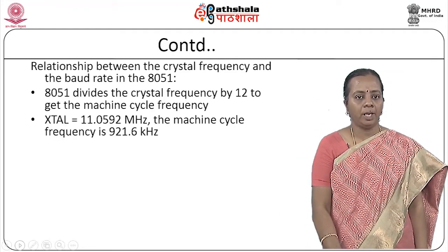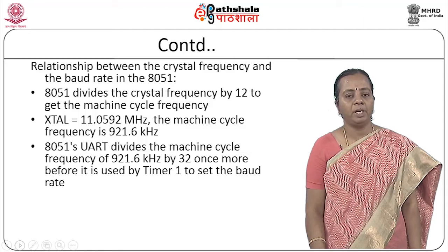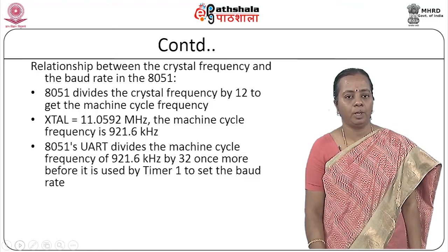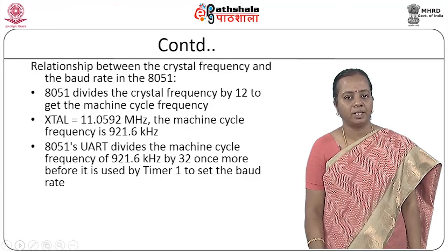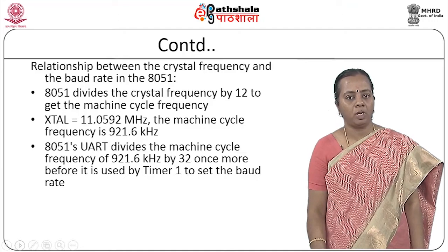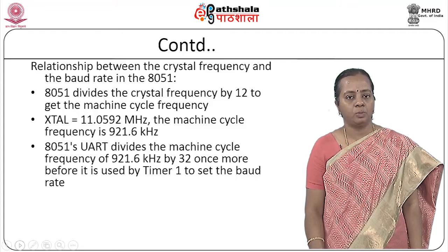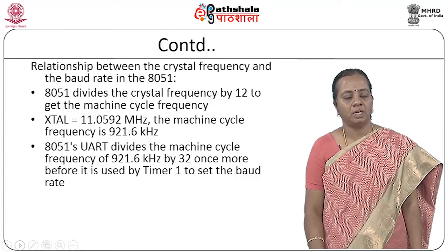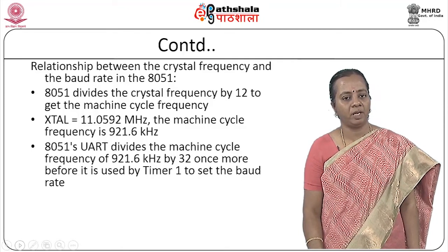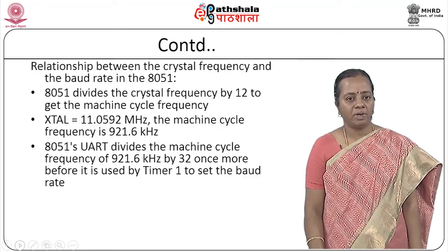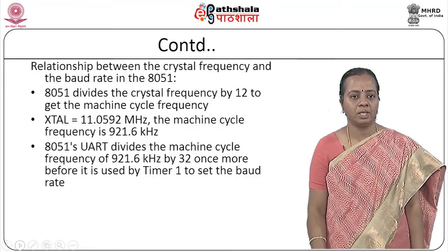Now, looking at the 8051, we will see how to configure this baud rate, which is very important. We know there are different oscillators inside, and the CPU clock cycles generated are different. We have 11.0592 megahertz as one particular crystal oscillator, and maybe a 12 megahertz oscillator, a 16 megahertz oscillator, or even a 20 megahertz oscillator. For our example, we will take the 11.0592 megahertz oscillator which generates the CPU cycles in the 8051.